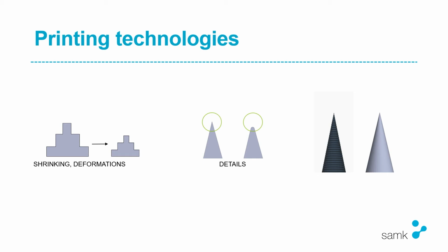They come out as dull spikes, but if it works that way, then it's good. And with plastic, the details can be around 0.3 to 0.7 millimeters. That's the detail level that can be achieved. With plastic, you can get a pointish tip, but it will look a bit more like the one on the right that is circled.